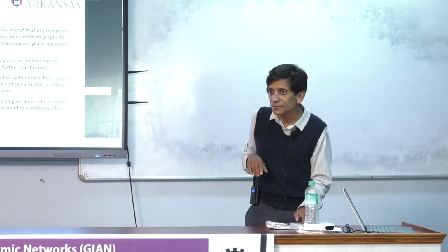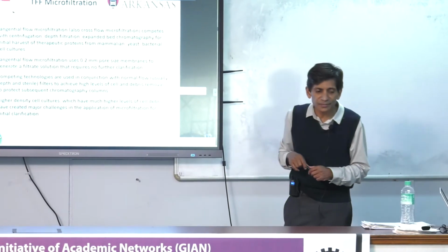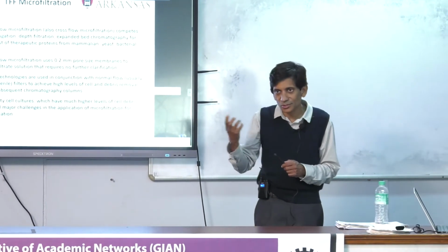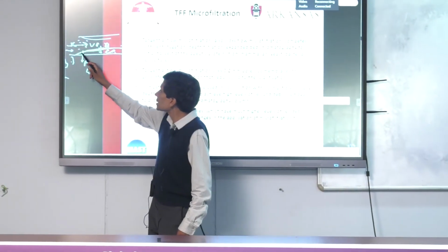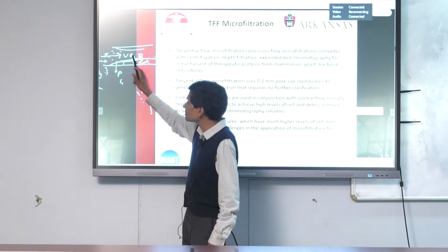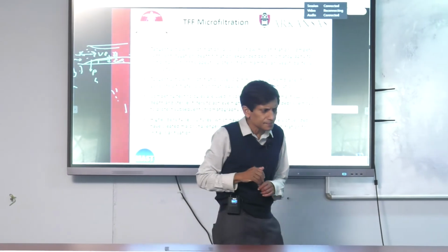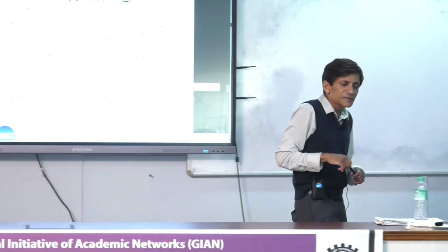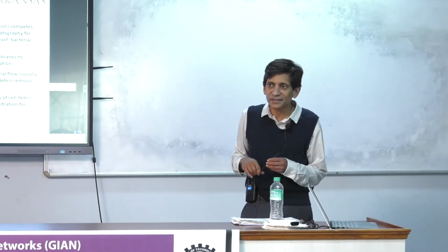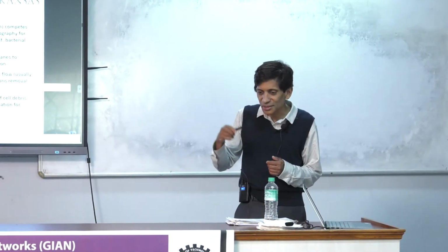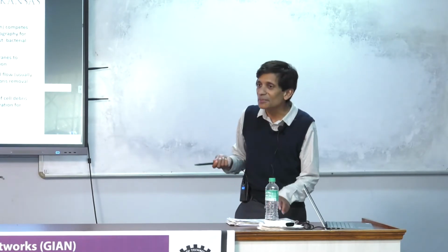So people did this for microfiltration, and they had a problem because you end up with something called the flux paradox. That's what it's called in the literature. And that was this. You can do these predictions and say, okay, you can look at the convection this way, and you can look at Brownian diffusion this way, and you can predict your permeate flux. That can be done. Unfortunately, the permeate flux you predict is smaller than what you observe in reality. So that's one of the rare cases where actually in reality you get a much better result than you predict. So this is a problem.